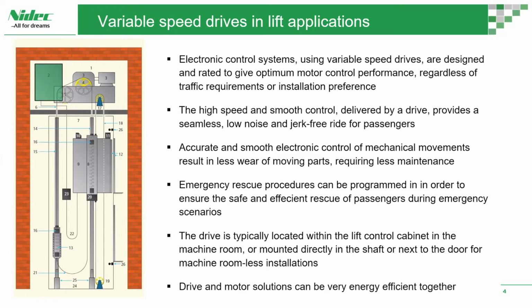Physically, the drive is typically located within the lift control cabinet in the machine room next to the lift controller, but it may also be mounted directly in the shaft or next to a door for the more modern machine room-less installations that have been quite popular in recent times.